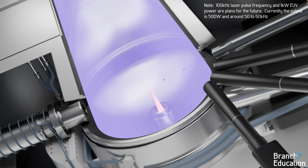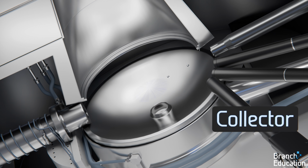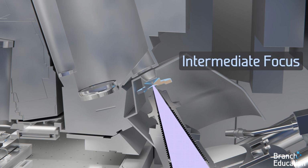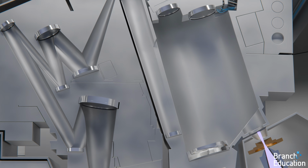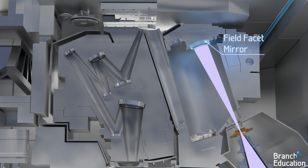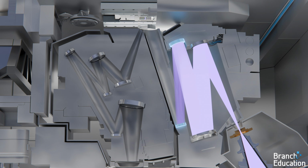Now that we have EUV light, the first mirror, called the collector, focuses all the EUV light to a small hole called the intermediate focus, which only EUV light can pass through. The light next enters into the illuminator, which is composed of the field facet mirror, the pupil facet mirror, and another set of mirrors.